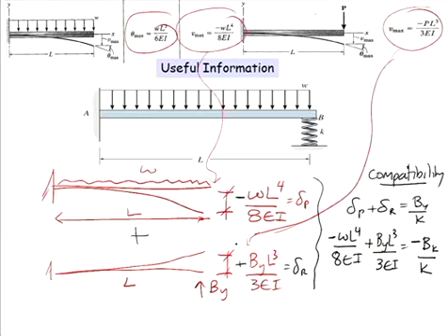When we find W, we use the ULS, because we're trying to find the Z value, which comes from the moment over the stress value. Once you get the stress, you take it as 350. When we use WL squared on 8, we use W as the ULS, and we took not just the self weight of the beam but the concrete and everything on top of it. You don't need to iterate for the secondary beam, because there's nothing else to iterate to.